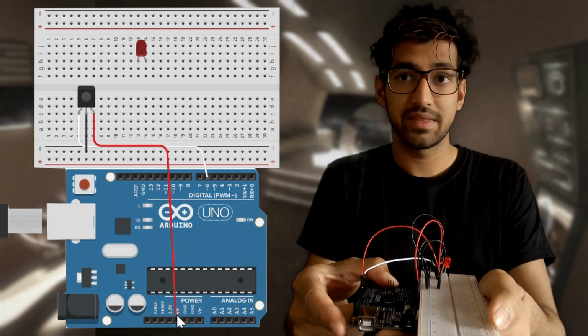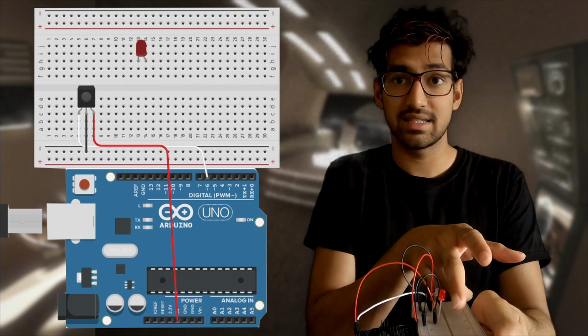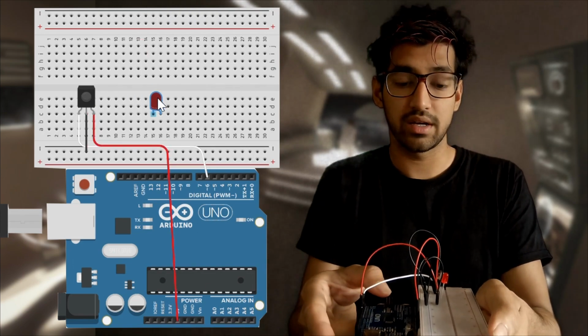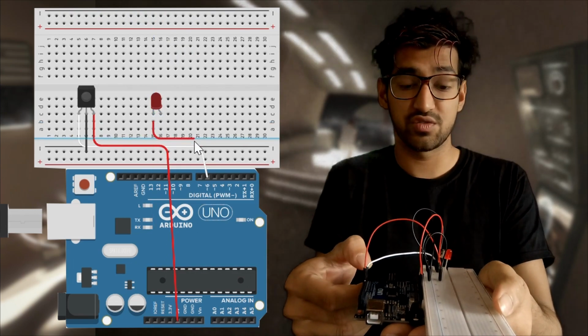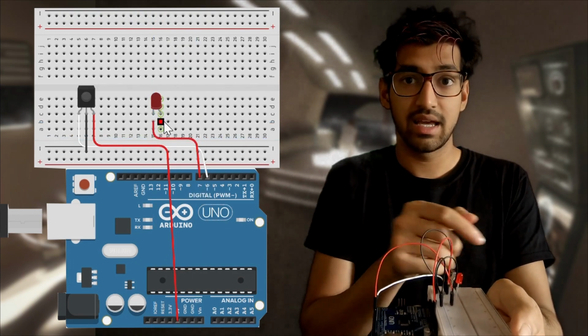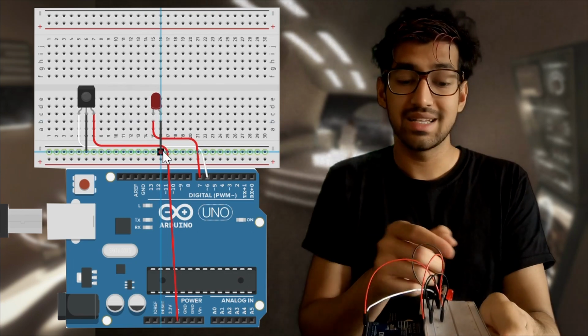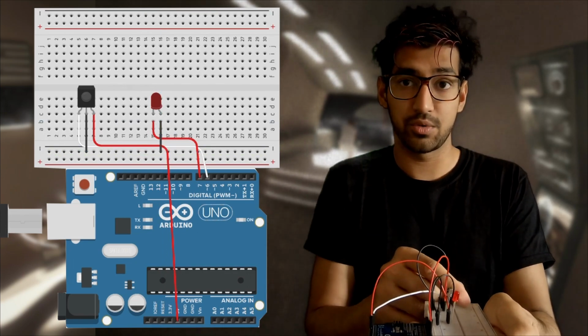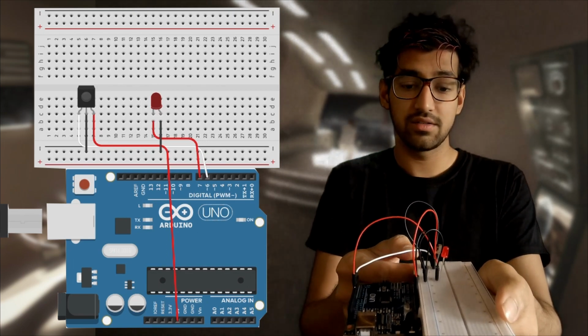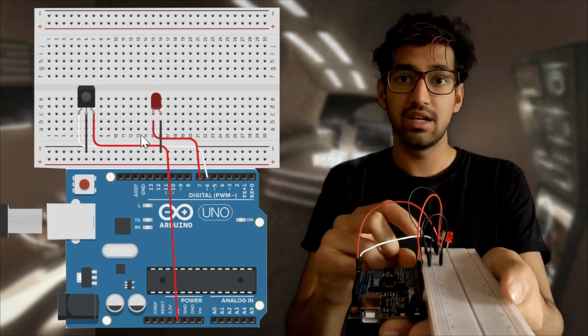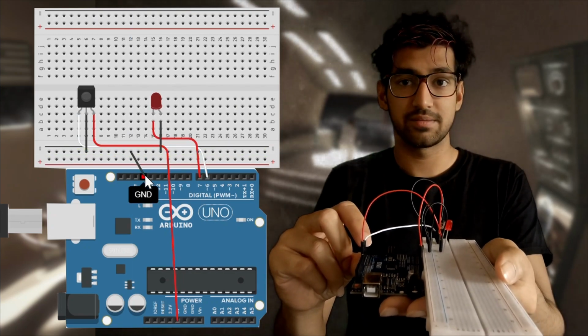Connect the LED at 15C and 16C. Connect a red wire from 15B to port 7 on the microcontroller, which will be powering the LED. Connect a black wire from 16B on the breadboard to the negative on the breadboard. Connect a black wire from the negative of the breadboard to the ground in the microcontroller.